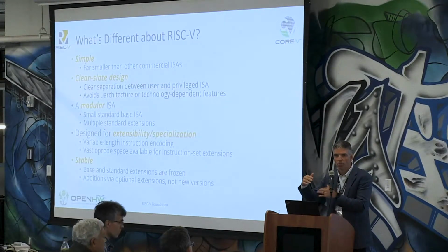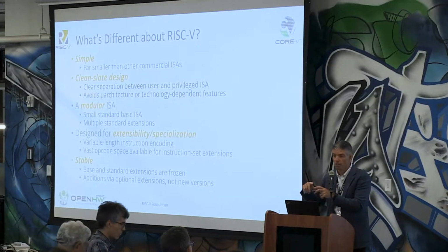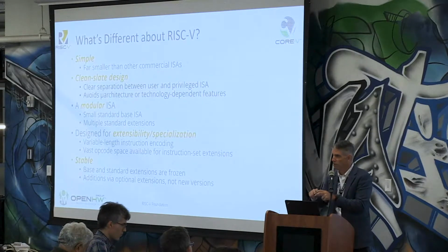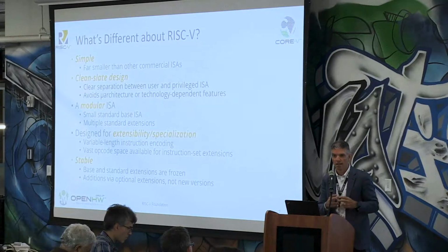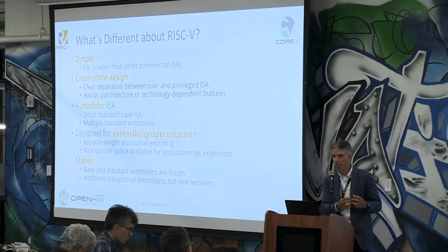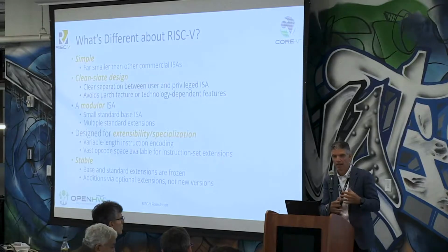The standard is broken up into, or the specification, I should say, is broken up into standard extensions. Which makes it really easy to tailor your design to the right performance metrics that you're trying to hit for the data payload that you're trying to target this device for. And that modularity is leveraged by allowing for user-defined instructions as well. So there's a space in a reserved section in the opcode space where you can roll your own instructions, whatever secret sauce algorithm that you want to have in hardware, implement that machine, kick it off with a custom-built accelerator as an example through the user-defined space.